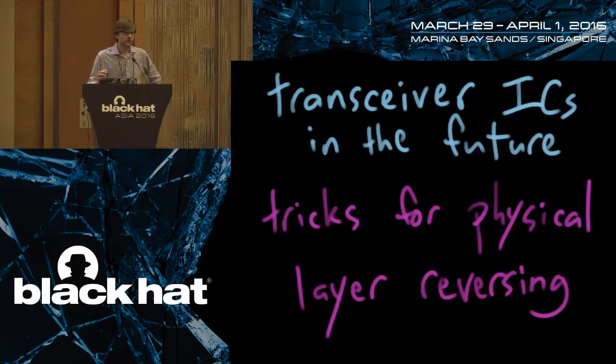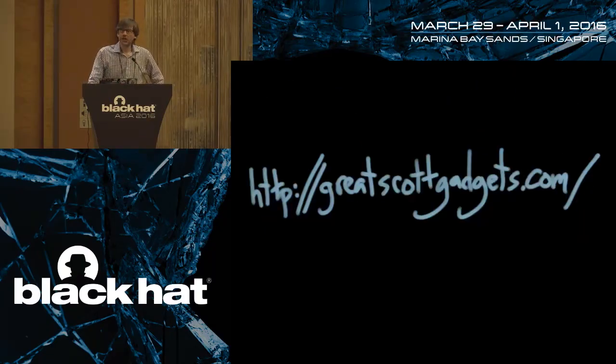But we might also have better tools for reverse engineering just using the transceiver ICs in the future. In particular, I've talked with some folks about some tricks we could use with things like the Yardstick 1 to do reverse engineering of the modulation and the data rate. But primarily those tricks are things like try a whole bunch of different modulations and see what works, try a bunch of frequencies and see what works, try a bunch of data rates and see what works, or oversample and then figure out what the periodicity is. It's kind of hackish, and so in the long run, I think SDR will win.